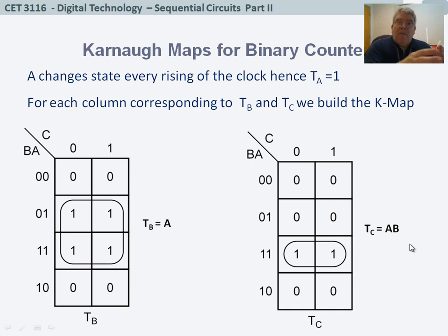Perfect. So we now have one step guaranteed that we can develop using K-maps, and it's not guessing, as we sort of did before, but just a procedure that takes us step by step into the design. All right. Now let's see another example, which is a redesign of the same counter, but now using D flip-flops.